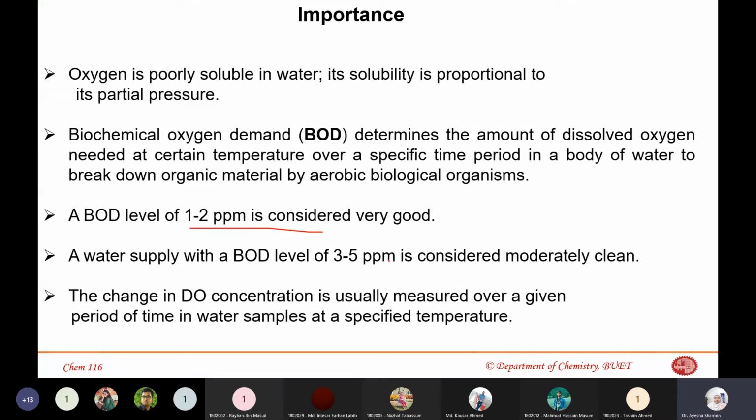If it exceeds 7 ppm or something, that means your water system has to be cleaned for the algae. Otherwise, you can have toxins. If the algae is cyanobacteria, you might get toxins in your water supply. Okay, so it's that bad. It is that bad. And sometimes in Australia, I think they had to shut down their water supply system because of a cyanobacterial bloom that exceeded this level.